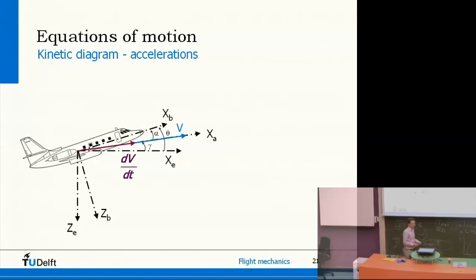Now there may also be some kind of a vertical acceleration. And you know that if you have an acceleration perpendicular to the speed vector, then you will start to go in a circular motion. So basically, if you're in a car and you're driving straight and you make a force to the right, then you start to go in a turn to the right, really simply. So you can imagine that there may also be a vertical acceleration of the plane, and such a vertical acceleration will make the plane go in a circular motion like this.